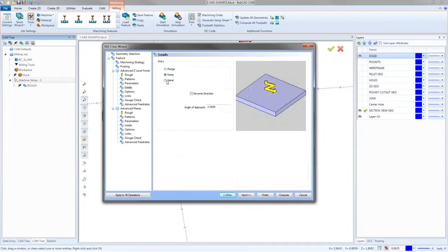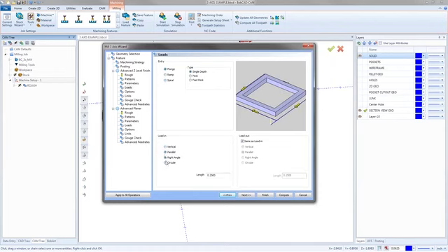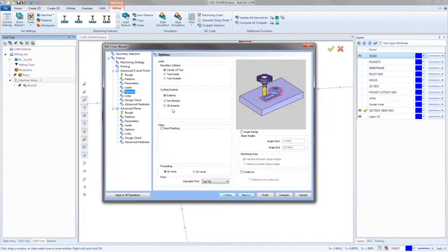All right, here we've got our leads, just how we enter into the material. We've got the plunge, the ramp, the spiral. With the plunge, you always get lead ins and lead outs on your finish passes. There's no cutter comp, but you do have leads for it. Options, boundary options. So I have a boundary. I want the center of the tool to stay on the boundary. So the center of the tool, if it hits the boundary, that's when it's going to stop.